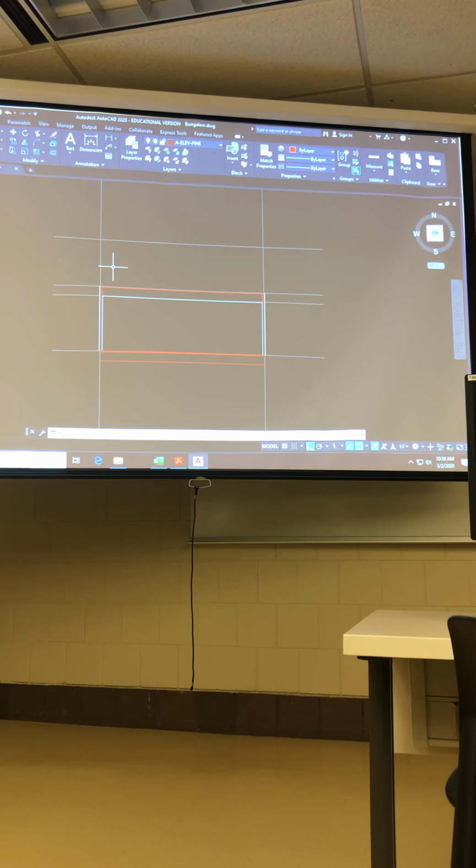Oops, I'm sorry, we actually have a 12-12 pitch on this one. So I get to show it to you a second time, how about that? Wait, you hit the shift key and 2? Okay, let me show it to you again. Okay, I'm going to start from that work point, the end of the line, and I've given my base point. Now I'm going to enter shift 2, which gives me the at symbol. I'm going to enter 12 feet, comma, 12 feet. And there's my 12-12 roof pitch, drawn absolutely perfectly accurately right from there.